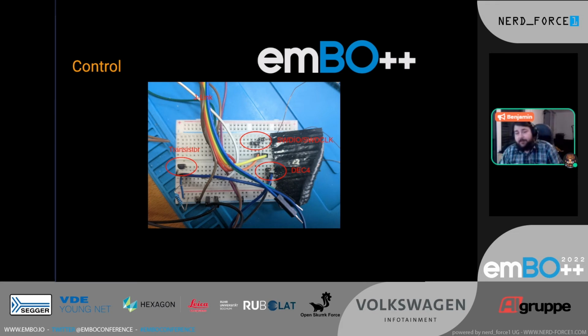And this short will actually discharge the capacitor really quickly and then drop the entire voltage down really fast, really reliably. And once the Bluepill board releases the pin, so it goes back low, the transistor will stop conducting, the voltage will recover, and the chip can continue executing. This is just a way to reliably drop the voltage.